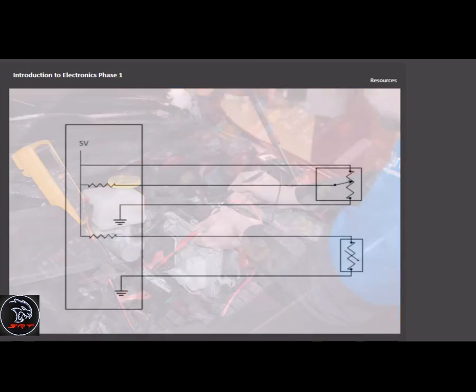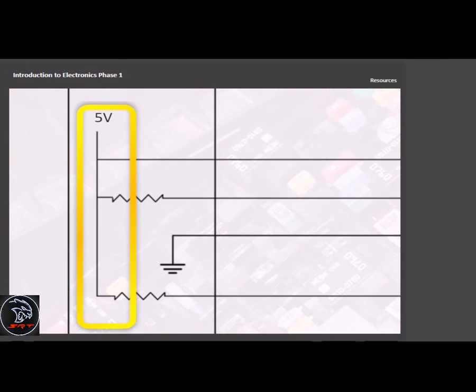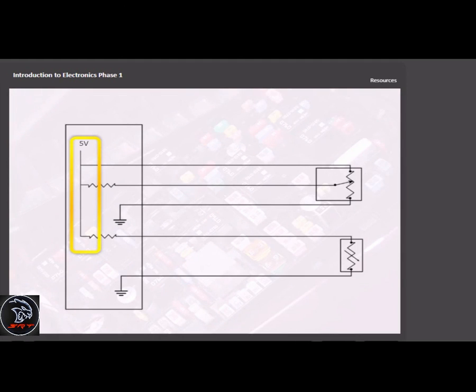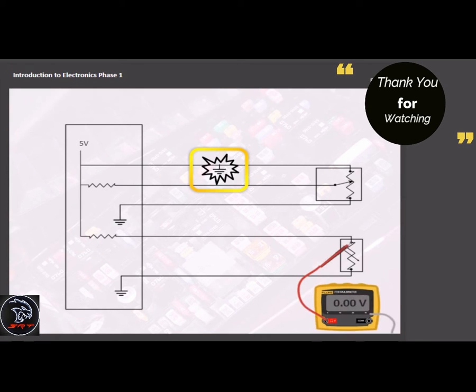Reference voltage produced by the module is often used for multiple sensors and is typically a shared circuit within the module. This shared connection is not always obvious because the common connection is seldom shown on wiring diagrams. This means that if the VREF circuit is shorted to ground at one sensor, it can cause a loss of reference voltage for other sensors using the same internal supply.